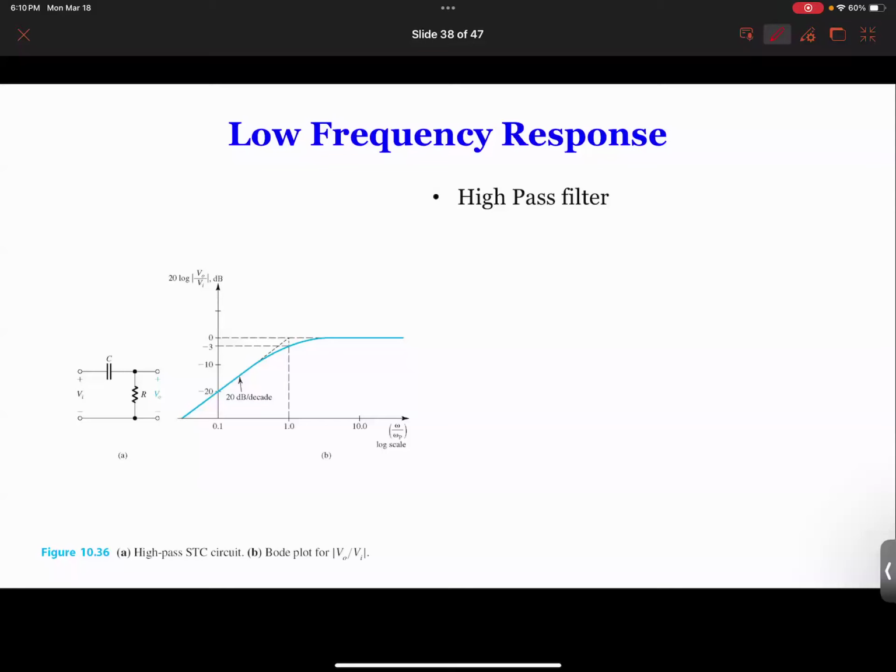And you can look at your output. You're going to see the sine waveform start small, increase, and then decrease. So now you know that's the middle band. But it's hard to know where exactly this thing is going to be stable, right? So that's why you need to do a frequency response sweep.